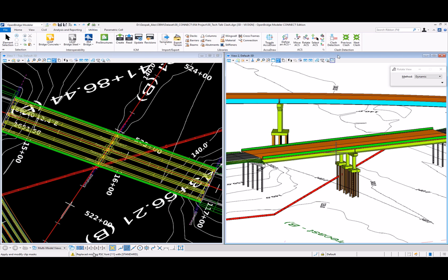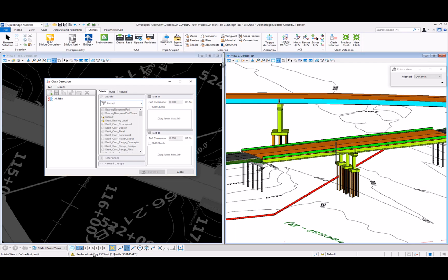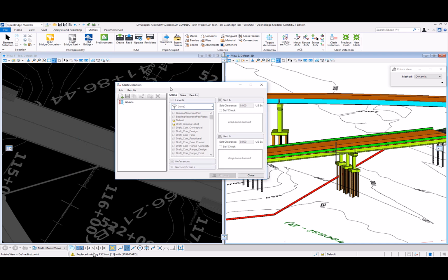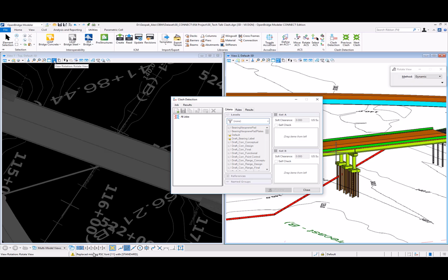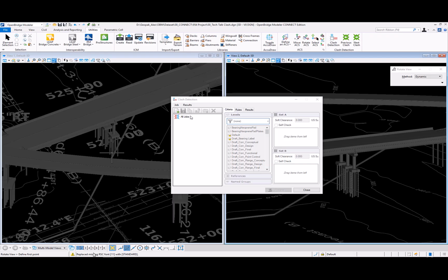So I just did a very quick clash detection, but there may be hidden ones where I need to calculate the distance more precisely. So I use the clash detection tool present in the platform, right? So I invoke that tool and I will create what is called a specific job. Why is it a job? Because it could be saved. As I'm designing, these jobs could be run every time some new information comes to light. So I don't need to do the setup every time. I just save it as a job, right?